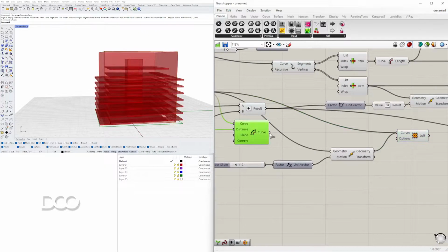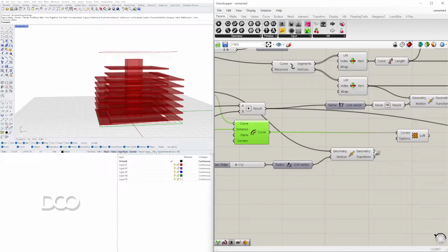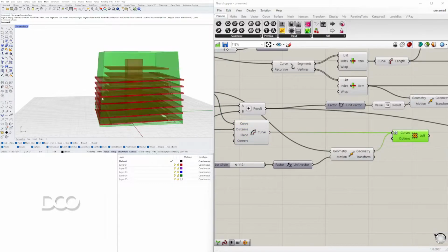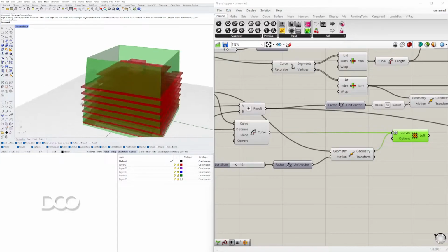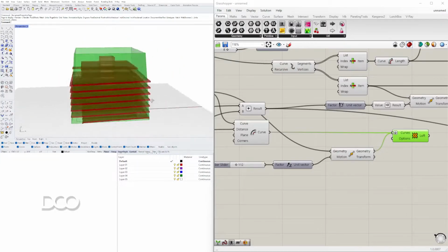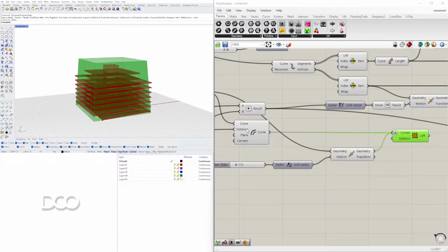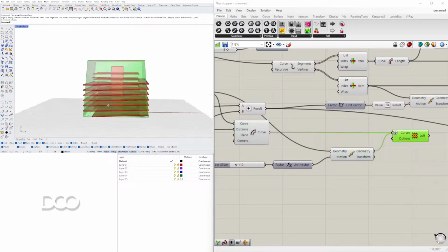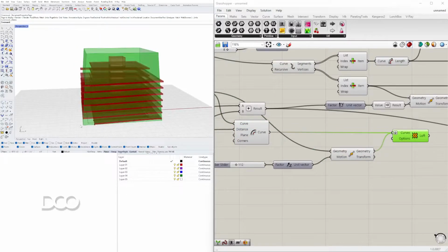That's actually incorrect. It's actually this outer one first, and then I'll hold down shift to add this one. Now I'll type in flatten for sure. This way it works. Otherwise, sometimes when you create an offset or a move, they have an issue lofting together. But now with this, we can take this outer line, move it up by that same amount, and create a solid.